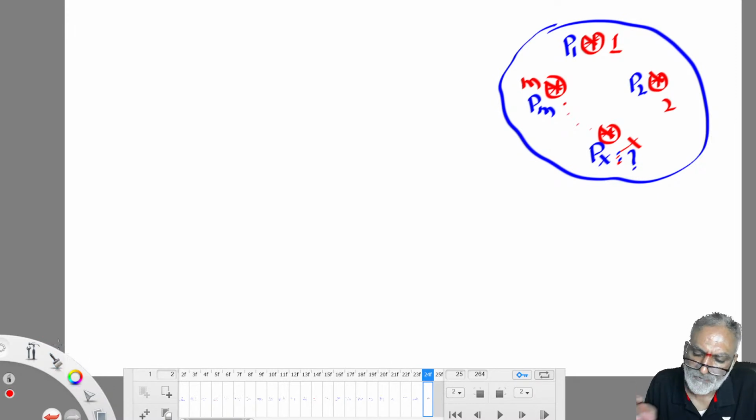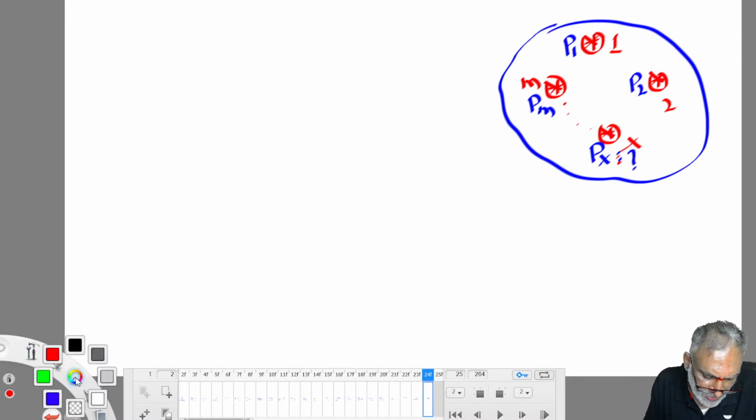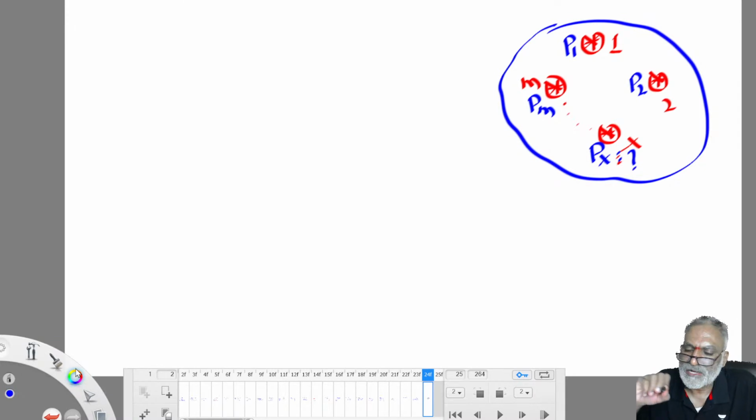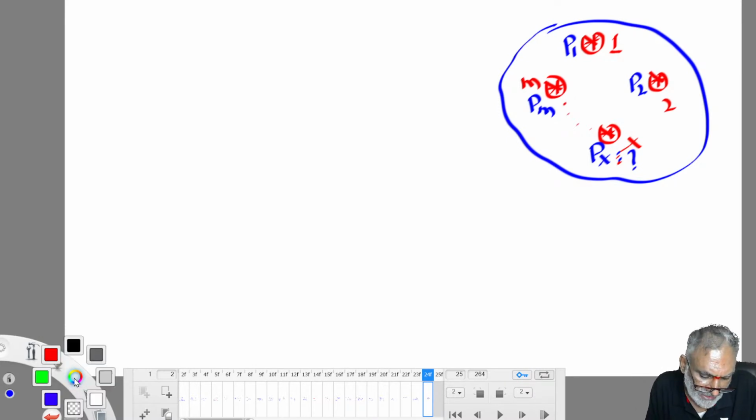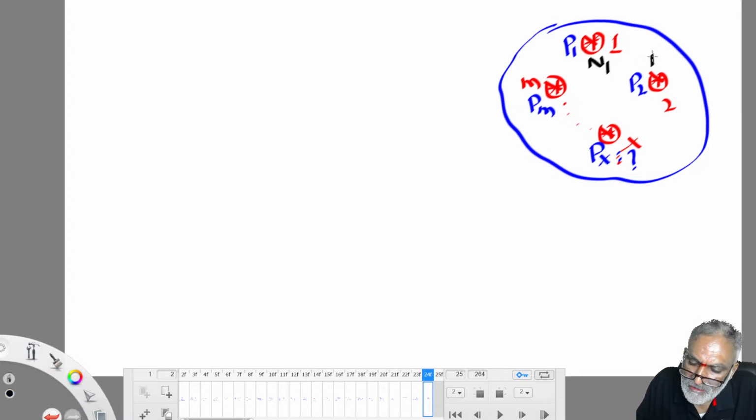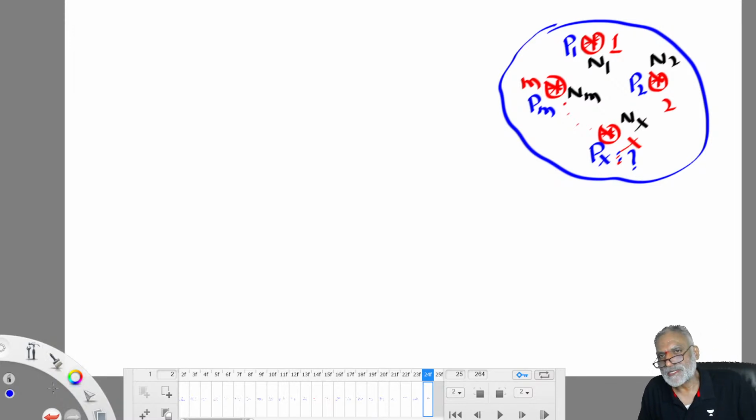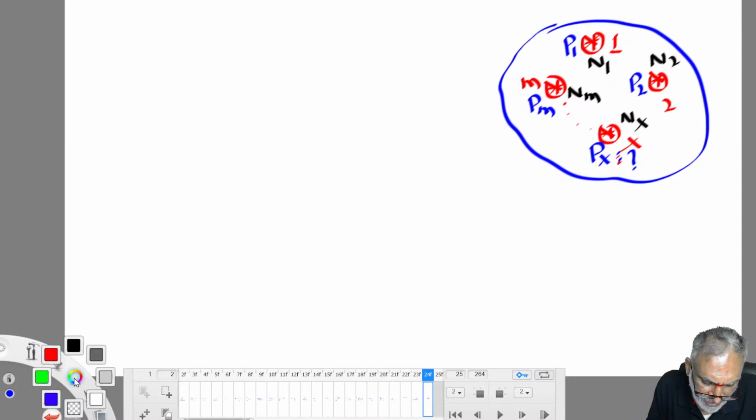To work out that missing rainfall data at rain gauge station X, we require two kinds of data. The rainfall recorded by other rain gauge stations during the same time period when station X missed recording rainfall data. We also need the normal annual rainfall data of all adjacent rain gauge stations to station X. The normal annual rainfall data is denoted by N values. So N values record the normal annual rainfall data of all rain gauge stations including station X. The latest 30 years average annual rainfall data is known as normal annual rainfall data.